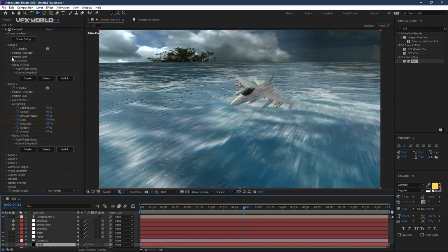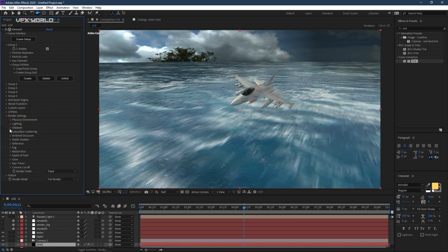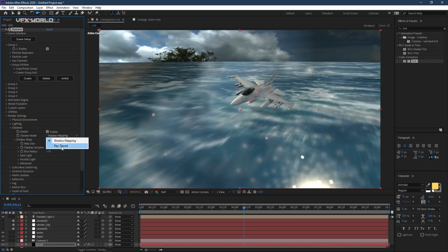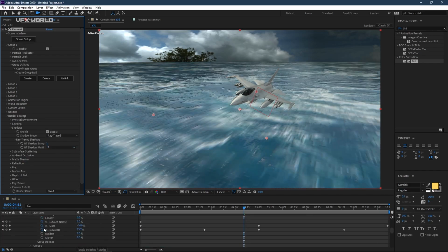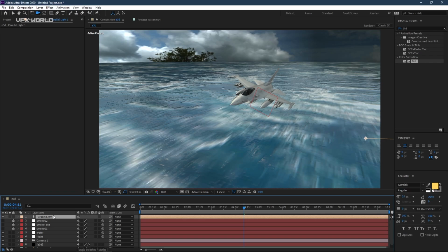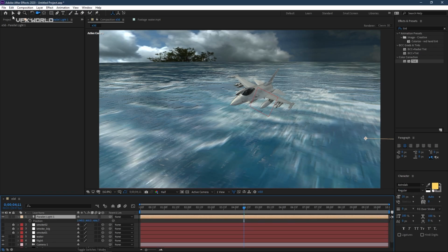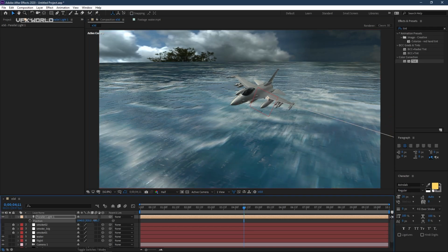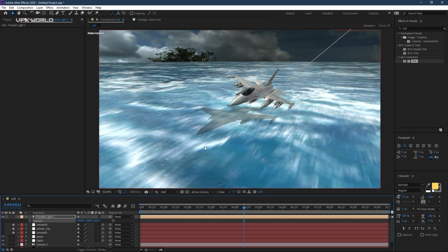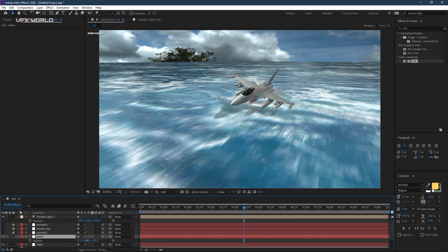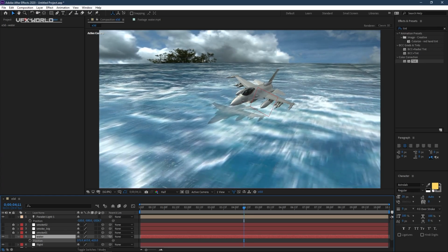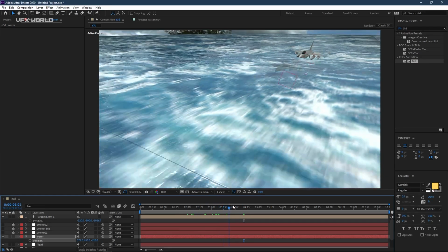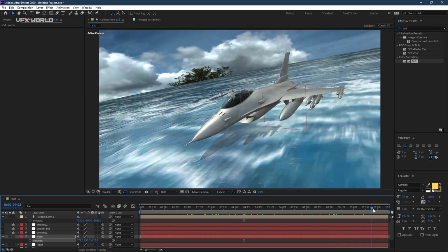Now select element 3D, and let's go to this render settings, and here you can find this shadow. Turn this on and make it to ray trace shadow. You can exactly see everything is changed up here. Now just go back to your light settings and press P here, and let's change the positions. But before that, I just want to take, and this should be coming up here. Now see, the shadows are coming up here, and now let's change the positions for the light. Now you can exactly see the shadows are coming up here, and in this case I just want to change the lights, not much, but so that the shadows are looking pretty nice. Yeah, that's it. So now the shadows are looking like this, and I think this is awesome.